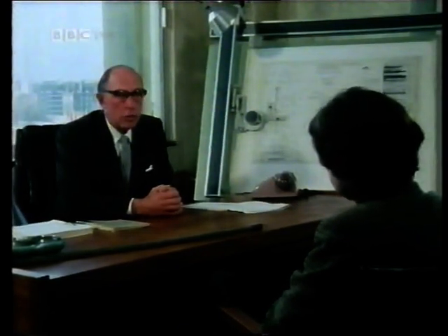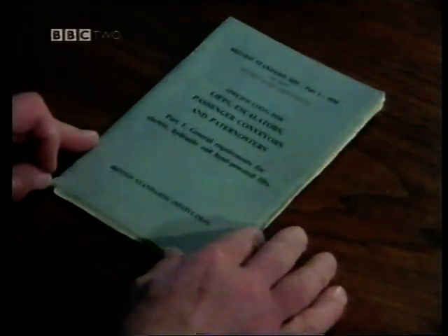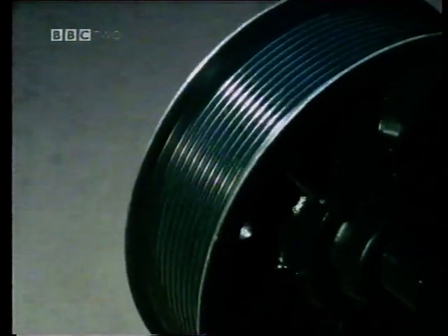Now, these safety devices are spelled out in considerable detail in British Standard 2655, General Requirements for Electric Lifts. This specification requires a minimum ratio between rope diameter and sheave diameter of 40:1. In the case of this machine, the sheave diameter was 910 millimeters, and we decided to use a rope of 16 millimeters in diameter. And thus you will see we achieved a sheave to rope diameter ratio of about 52:1, well in excess of the 40:1 required in this specification.